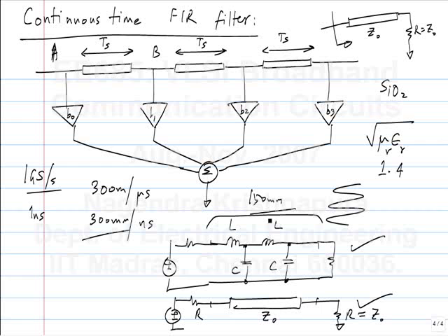Some of the problems with implementing this are, firstly, that the real transmission lines will have a loss, and certainly there is no hope of making a strip of wire and that acting like a transmission line, because you need a very large area to implement that. You can make lumped circuit equivalents, but even that will have a somewhat large area. And also the other aspect is that the inductance will always have a series resistance, or even if you make a transmission line, it will have a series resistance and it will have loss. Those are the two problems.